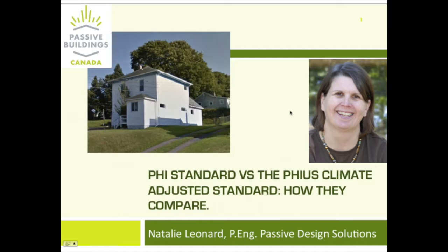Yeah, sure. There's actually a resource on the PHIUS website, somewhere in there under tools and resources, a spreadsheet that PHIUS put together, which has been extremely valuable in the energy modeling discipline, but also in evaluating which units to look at. A lot of Canadian HRVs dump the waste heat from inefficient fans into the supply air, thus bumping up the sensible recovery efficiency numbers, but the electrical use is really high.